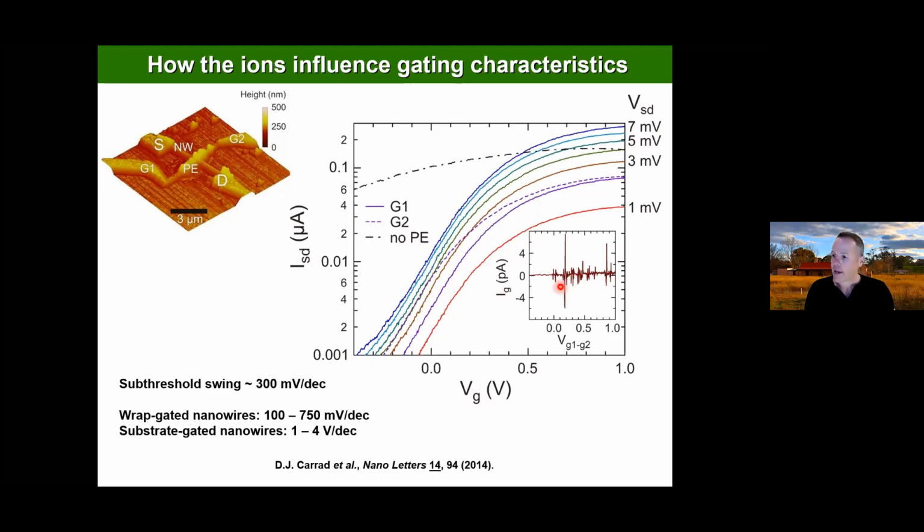Okay, and if you think about this just from a nanowire transistor perspective, this is really nice. You essentially get a wraparound conformal gate without the trouble of having to make a wraparound conformal gate, which if you're a device engineer is actually very difficult to do. And without having to worry about leakage from your gate to your channel, simply because your gate material is intrinsically non-conductive because it's using ions rather than electrons to work in here. So this is actually a rather nice structure.